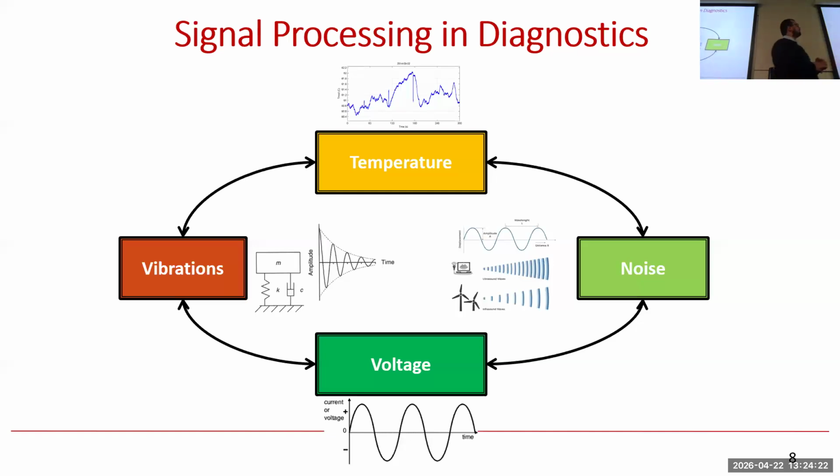What can be the main source of the information embedded in the signal? For example, we can monitor the temperature. With a failure, we have a higher torque, which goes with increased temperature, and noise as well. Another source is voltage, for example in the acoustic emission method with piezo sensors. And vibrations, for example acceleration of vibrations monitored with accelerometers.